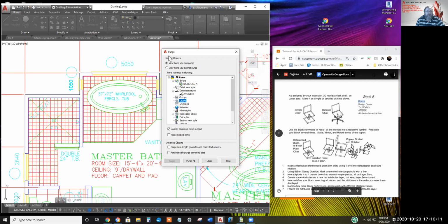I think there'll be a lot of blocks. No, okay, I'm sorry, I'm in drawing 2. I thought by exploding, oh okay, I exploded big house A, but all of the blocks within big house A are being used. My point is by clicking purge all repeatedly, you can, in theory, reduce the size of your CAD file. Now, I've never really noticed a decrease. It might take a couple of opens and closes before all the air bubbles shake out.